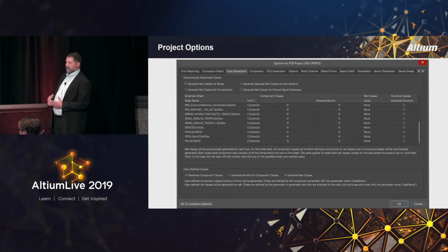And that's why you want to functional block your schematics. Don't put a USB circuit with your Ethernet circuit. They're two different functions. Put your Ethernet on one, put your USB on another, bring in two pages. They don't charge for extra pages.